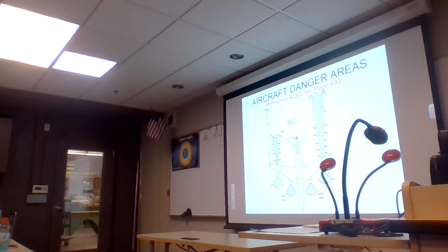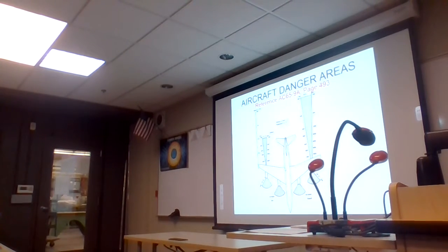This is important, even though it's not specifically about hydraulics. There are certain danger areas around aircraft. They show a turbojet aircraft here, or a turbo-powered aircraft, but we have similar hazards even with propeller-driven aircraft. The big thing we have to be worried about is the exhaust of the aircraft engine and also the intake area. If we're talking about a turbine engine aircraft, sometimes the exhaust area that we have to be concerned with is anywhere from about 200 to 350 feet.